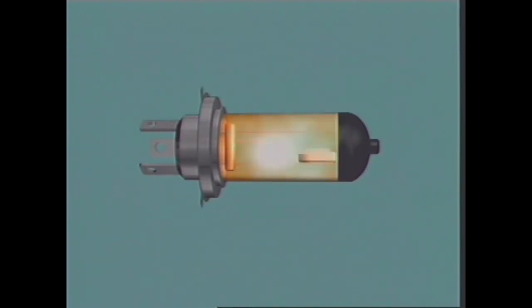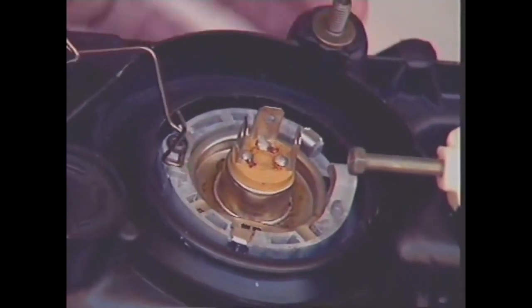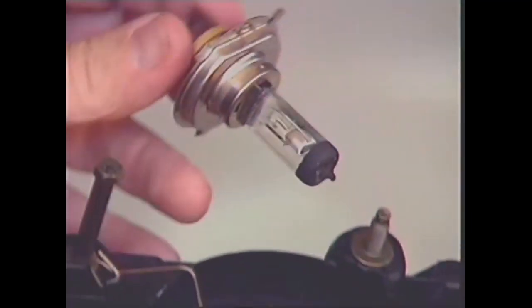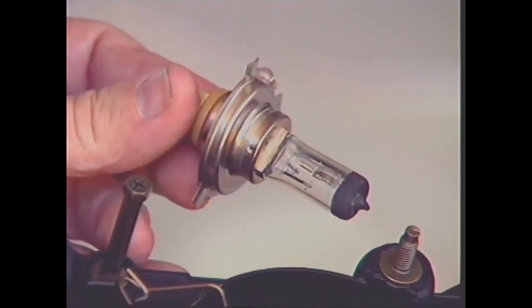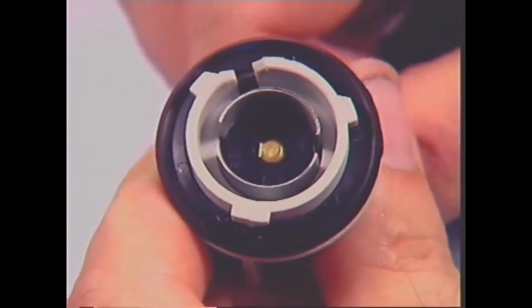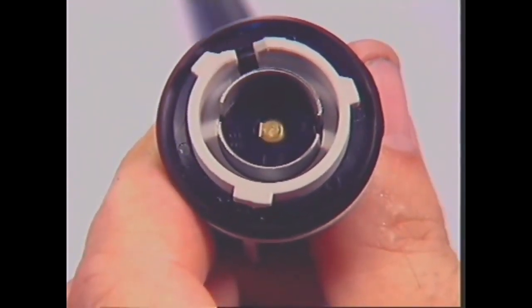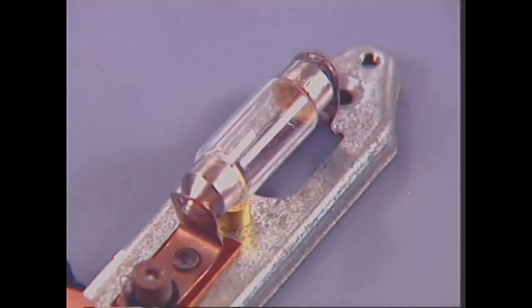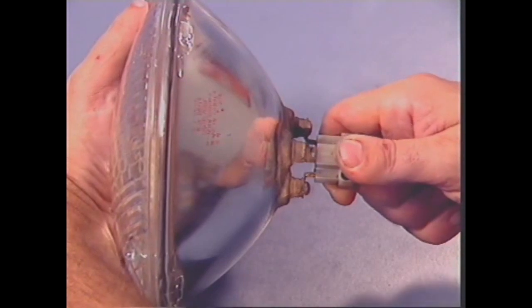Any tungsten that is boiled off by the high temperature is kept in suspension by the gas and is deposited back on the filament to extend filament life. Commonly used in headlights, they are referred to as quartz halogen, quartz iodine, or tungsten iodine lamps. The lamp circuit wiring is connected to the bulb by means of spring contact plungers or by blades which touch the bulb contacts, or by electrical terminals held in place by friction.